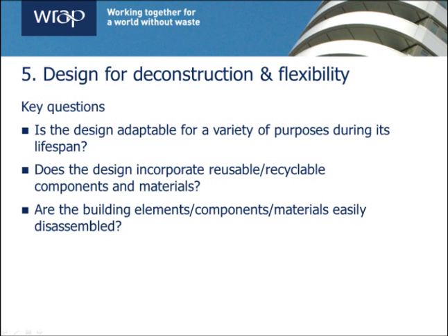Many buildings are converted for different uses during their lifetime. Waste will be minimized in this process if buildings are designed to be adaptable. This may mean, for example, making services distribution readily accessible or screwing rather than gluing finished joinery such as skirting boards. Steel frames are more easily dismantled and recycled if joints are bolted rather than welded.